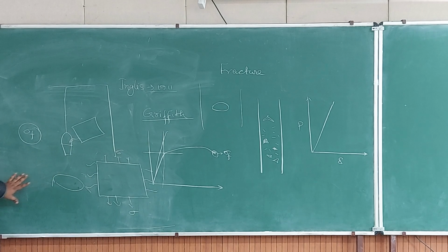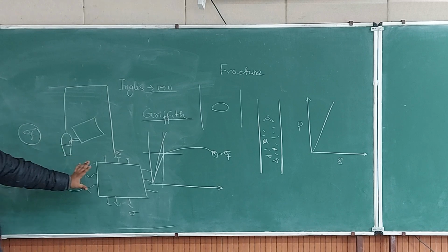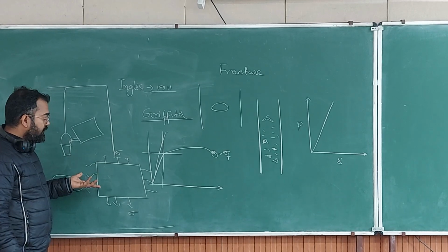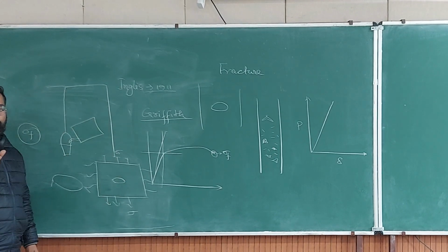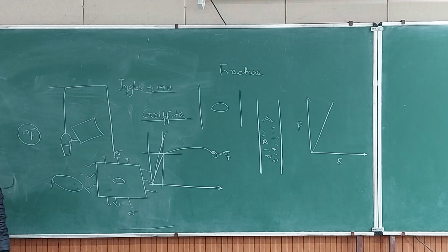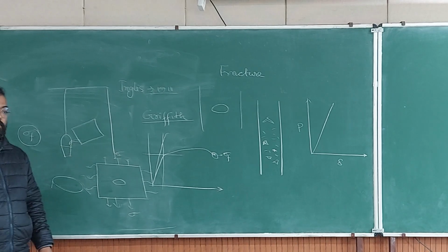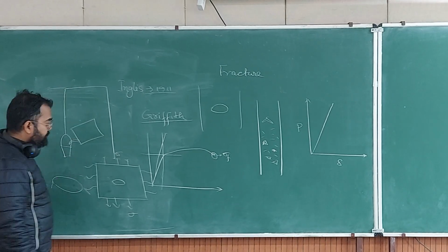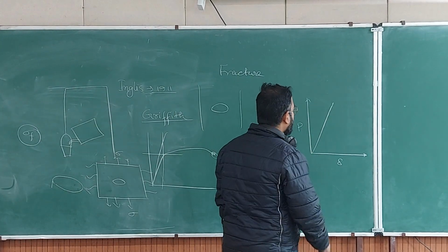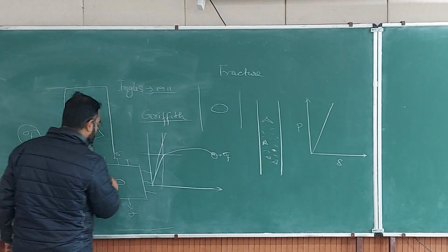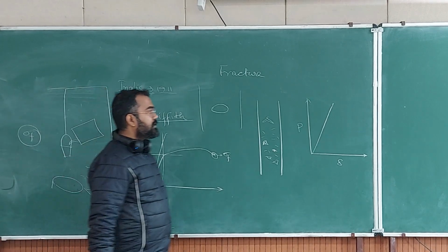Okay, so the width of the specimen is too high, so the effect of width is not calculated. Thickness is unit, and you have a hole which is elliptical, because if you use an ellipse in the equation, you can make it a hole, and you can make it a very sharp crack by changing the major and minor radii of the ellipse. So for this, if you load the sample, it goes to a certain height, and if the crack grows in the same sample by a certain amount, then the load will drop.